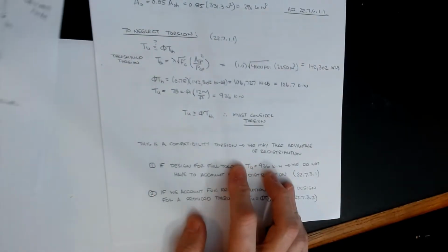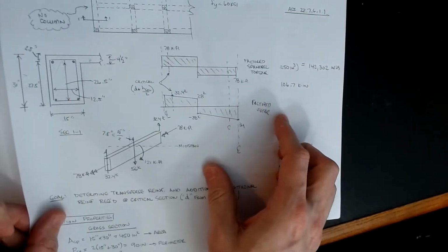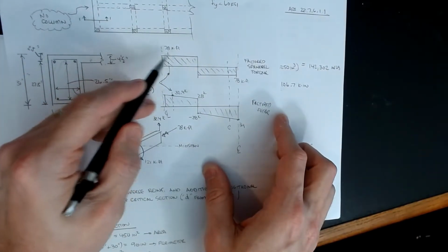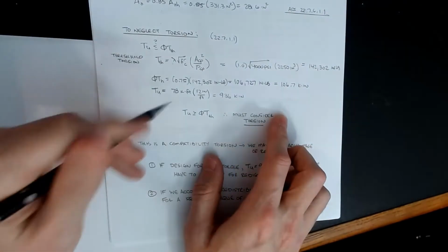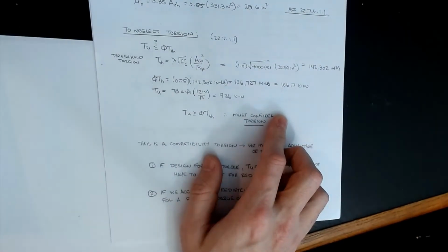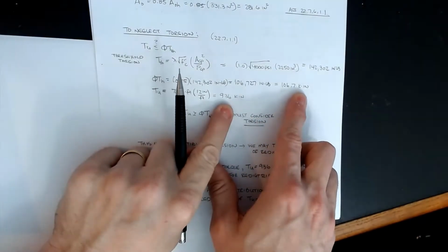Okay, all right. Now, the next thing that we do, in order to get my units figured out: remember the torque diagram that was over here was in kip-feet. And my design torque is 78 kip-feet, so I need to get that into units to be able to compare. So I'm going to take 78 kip-feet and multiply by 12 inches per foot. That gets me 936, and the units are kip-inches. And now I can compare these values.